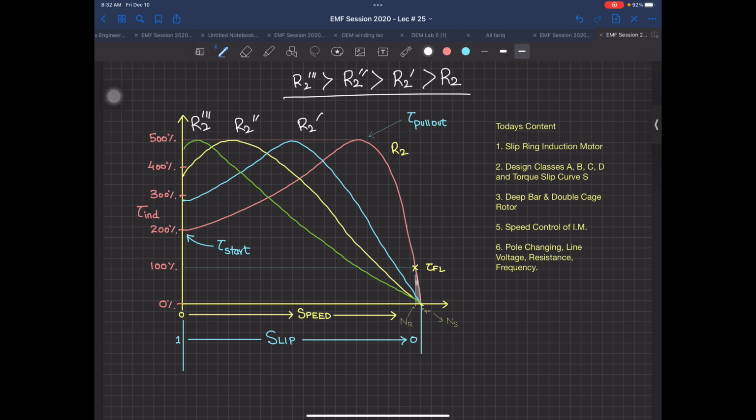If you're talking about a Nissan Leaf, a very good electric car used in the UK or Europe, or maybe somewhere in the USA also, in California, that car uses a synchronous motor, which we'll be talking about, PMSM, permanent magnet synchronous motor. And if I talk about a BMW i3 or BMW i8, which is a hybrid car, it uses a BLDC. The normal hybrid car in our Pakistan, the Toyota Prius, uses a BLDC also. So normally the talk of the town is BLDC.